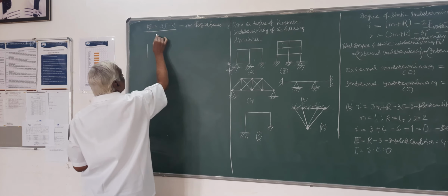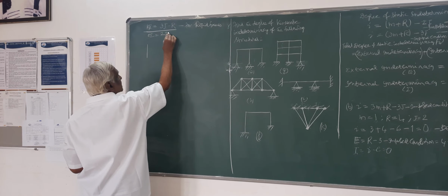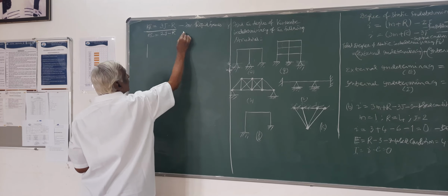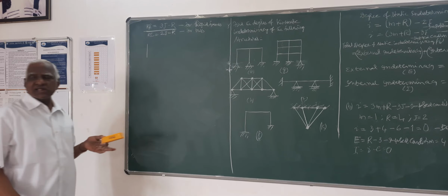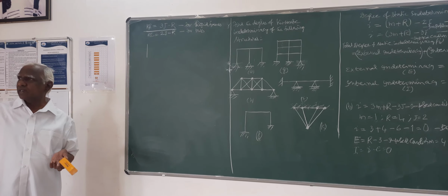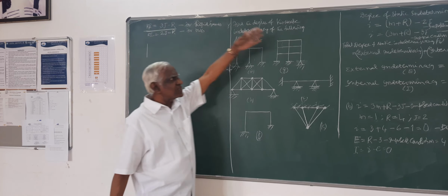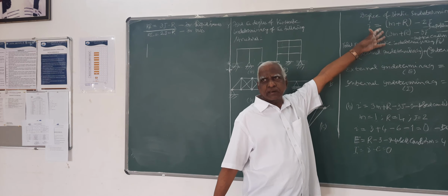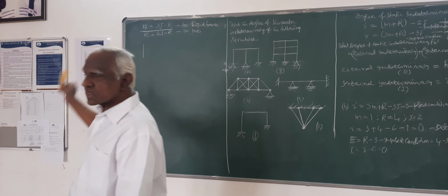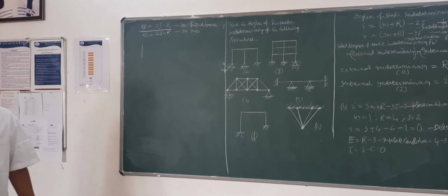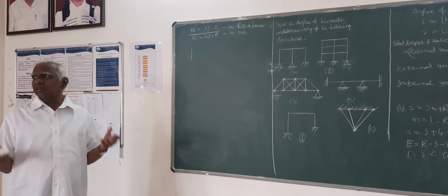And for trusses, you have only two displacements per joint, so 2j minus r. Moment we don't consider at all because each joint is a pin joint. Now we will remember the two formulas, as we did for static indeterminacy. This is the formula of kinematic indeterminacy. It is also called degrees of freedom, that is, freedom for motion or movement.